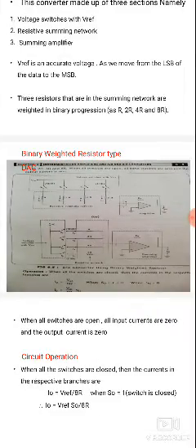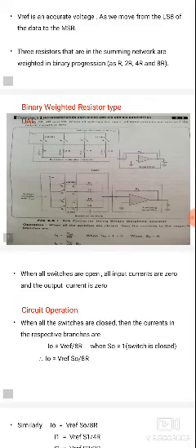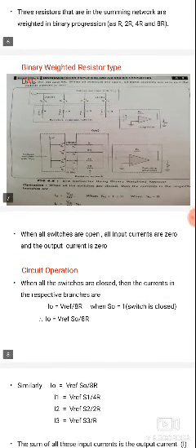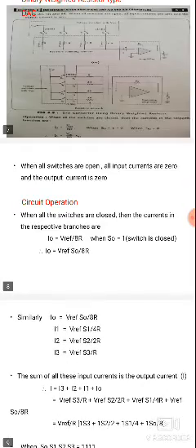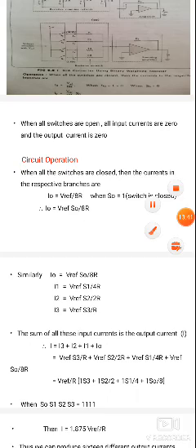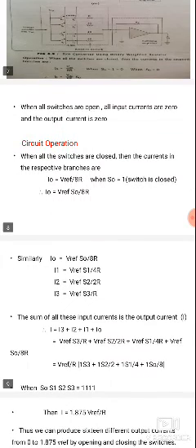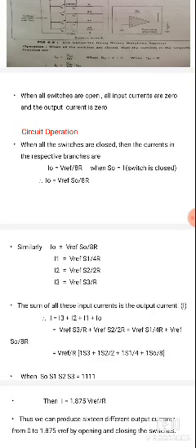So whenever the switch is closed, the respective current across the switch flows into the circuit, and the current depends on the resistor it flows across. Here the first switch, the LSB switch: whenever S0 is closed, the S0 position is indicating 1. The current across the S0 switch is I0, the current flowing through the circuit when S0 equals 1. So V equals IR, I equals V by R.